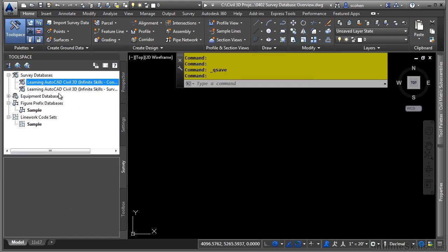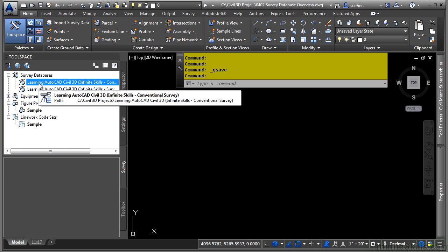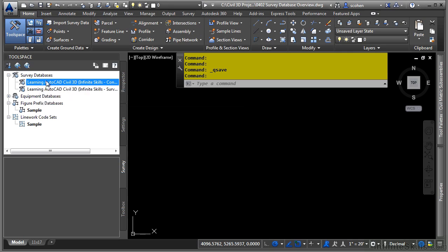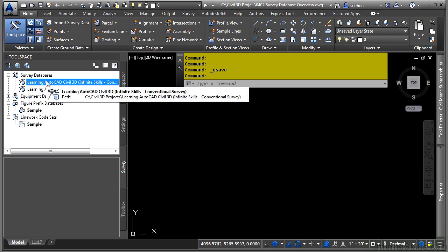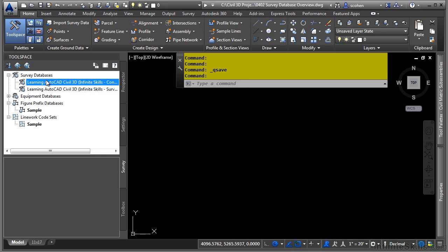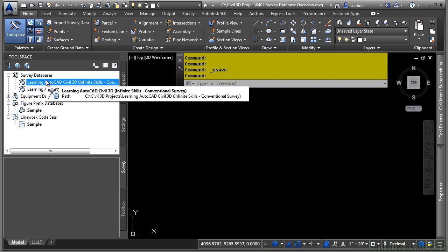That said, you can also store coordinate systems inside an actual survey database, and it can be different, so be aware of that. What's kind of cool about that is that it'll actually do transformations for you on the fly as you bring in data if the coordinate zones are different. However, if you do not want coordinate zone transformation, then this would be, of course, a bad thing.